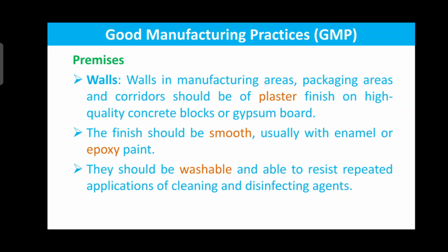They will not accumulate dust particles and microorganisms, and if they are smooth, then it is easy to clean them also. So even the walls have to be clean, not just the floors. Floors definitely have to be clean, but even the walls have to be clean. So, making the cleaning easier and so that dust particles should not gather there, they have to be of smooth finish. That is why you require a plaster finish on the high quality concrete blocks or gypsum board.